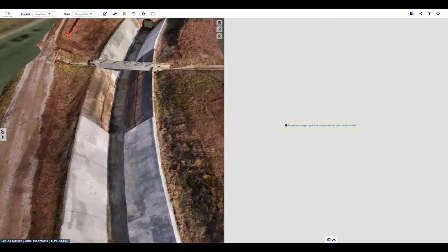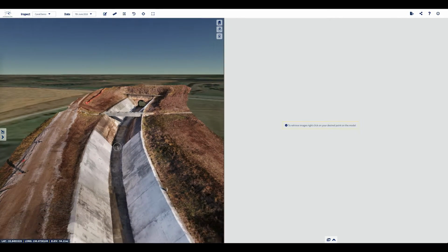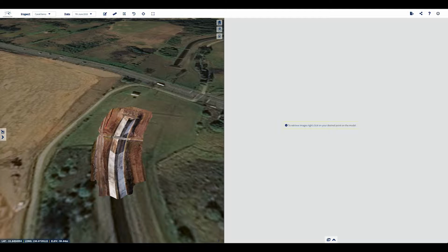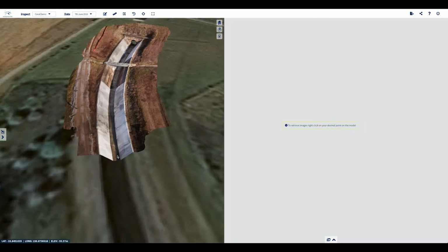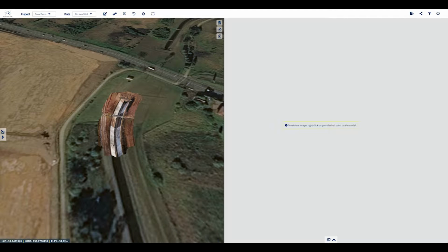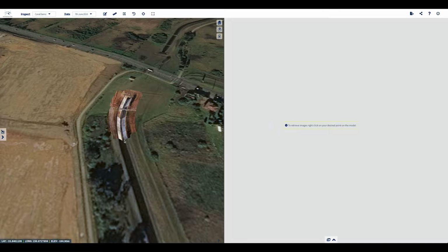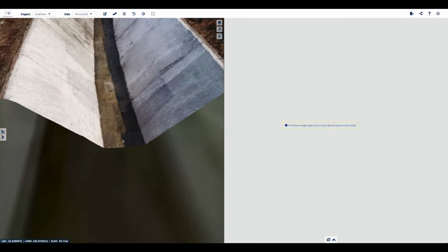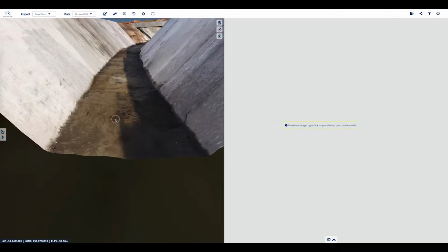It's pretty straightforward. So by way of an example, let's say we wanted to track up the base of this canal and observe the base of the canal from the start to the finish. We might start by zooming in on the start of the canal. The zoom will work wherever the mouse icon is. So if we move the mouse up here away from the model, that's where we're going to end up zooming in. So put the mouse where you want to zoom into, and you'll find that you can zoom right in on that part of the model and again rotate around.